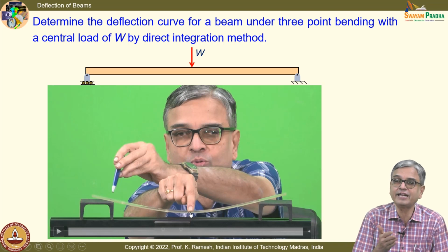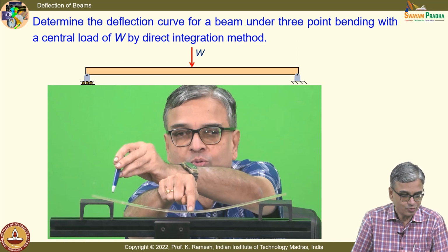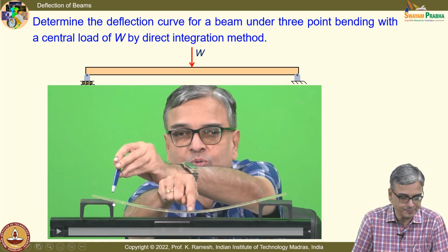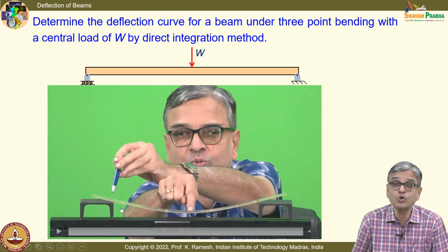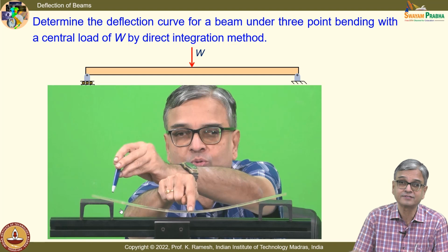Because you are going to write certain boundary conditions, you should know what the boundary condition is. We are going to discuss what will happen to the deflection V. You can say that this rests on the support, so the deflection is 0 here, the deflection is 0 here, but because these supports are pin jointed and freely rotate, you can have slope. Slope is non-zero. Slope can exist.